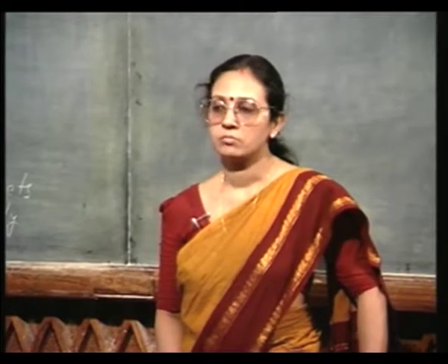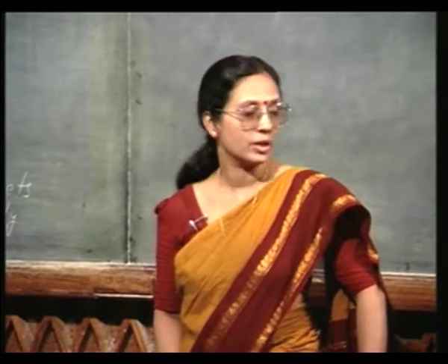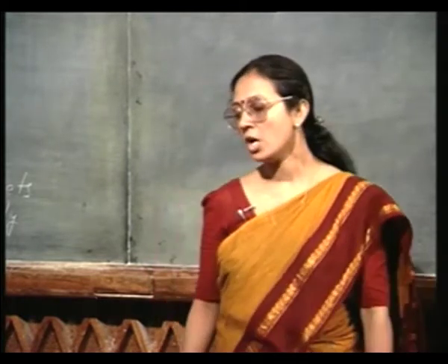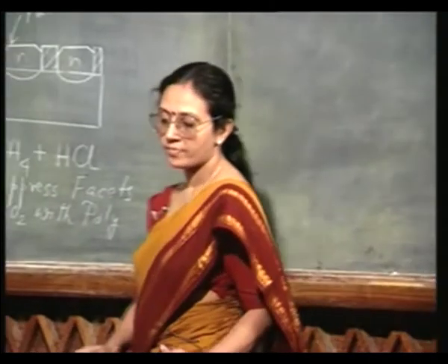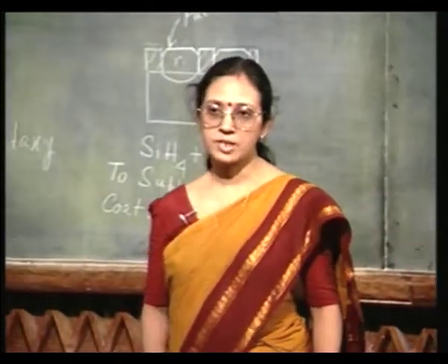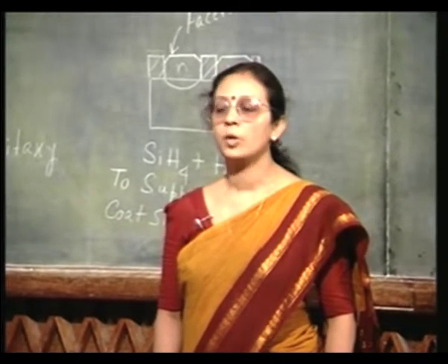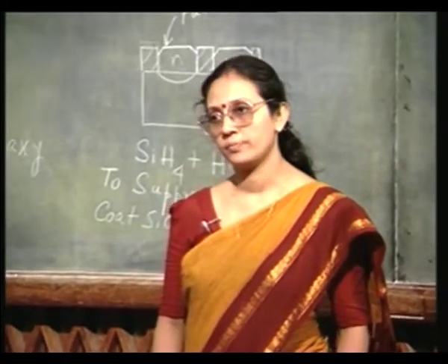All three of them, that is etching of the trench, then filling of the trench by polysilicon, and then the final oxidation step. So, this is a very important step in bipolar junction transistor fabrication, namely the problem of isolation.